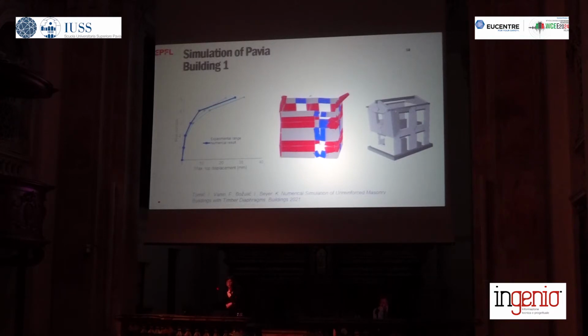Also in terms of failure mode, we are not too far away. I would say our failure mode is a little bit more gable out-of-plane failure than the first story, but even the first story is activated a little bit. You clearly see that the top spandrel opened up, so we see that also the in-plane walls are activated a little bit. So with that we can really say, well, now we have an equivalent frame model that at least can capture some of the out-of-plane failure modes. So the basic out-of-plane failure modes we can reproduce.